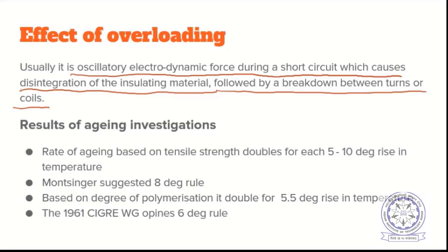Transformer fails due to lack of mechanical strength, or due to this oscillatory electrodynamic force which is happening due to short circuit, which causes the disintegration of the insulating material, and that leads to a breakdown either between the turns or between the coils.